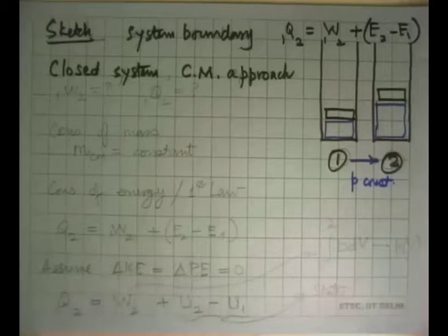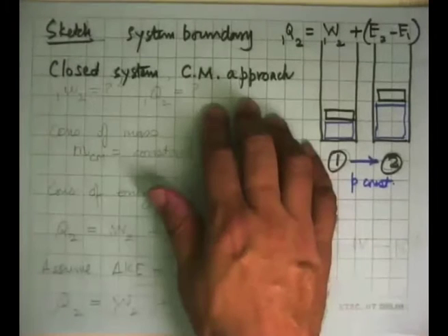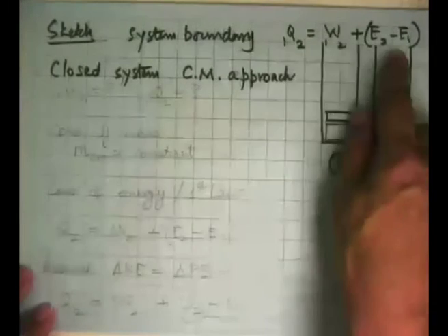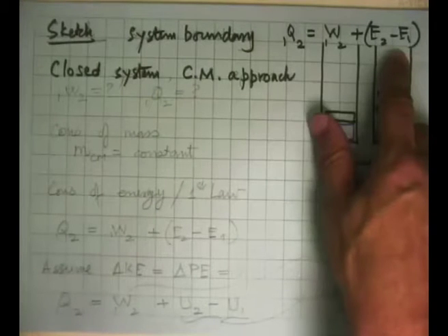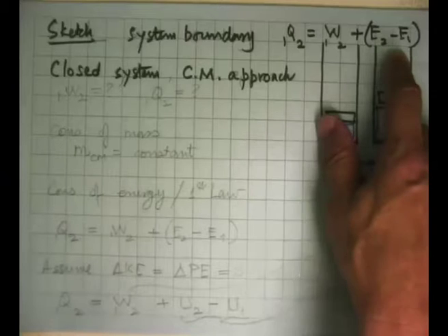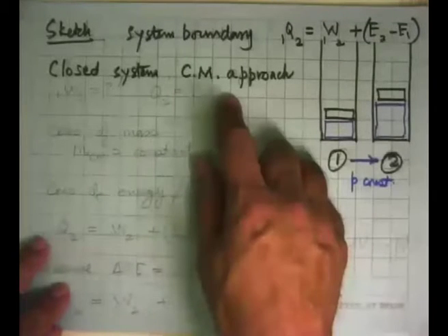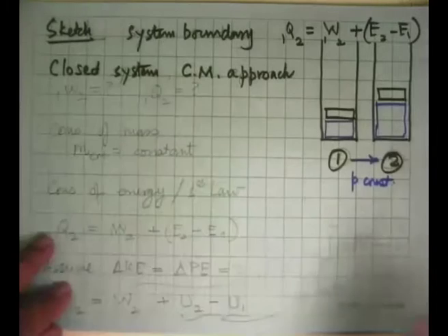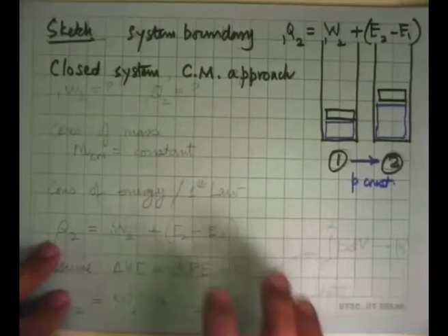It looks like a very simple thing to do, but I find that there are very many people who make a mistake right here. Instead of writing this equation, they will write Q dot CV is equal to m dot H1 plus m dot H2, all of that. So if we go wrong at this point, everything else is completely wrong.